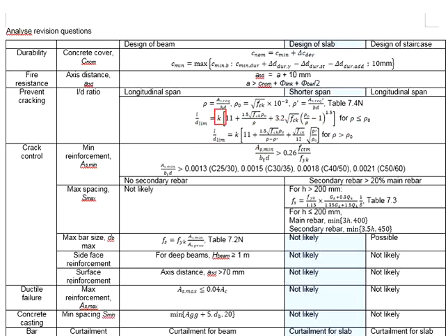As for the K, you can find it in table 7.4 of Eurocode 2. And the rho prime here represents the required compression steel bar areas over the effective area of that particular structural element.